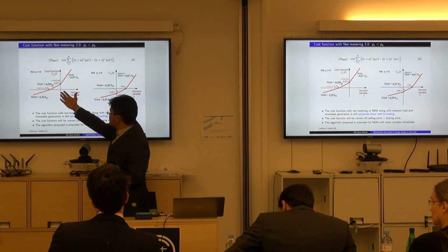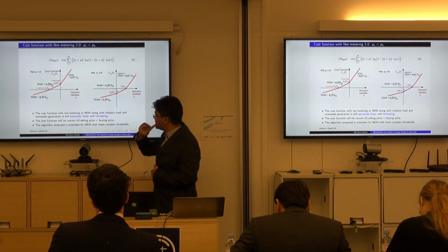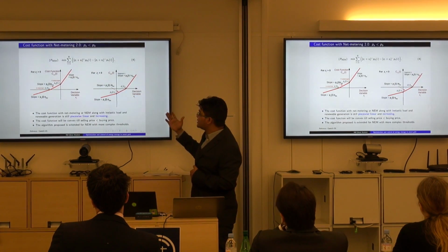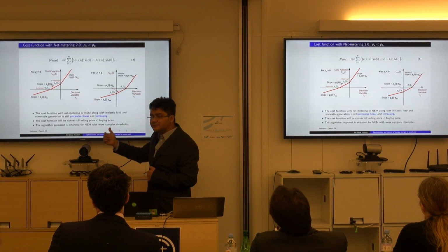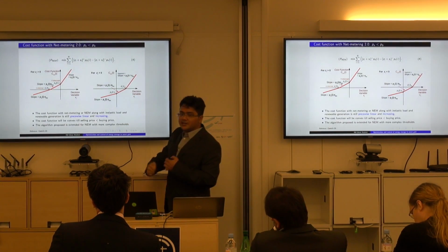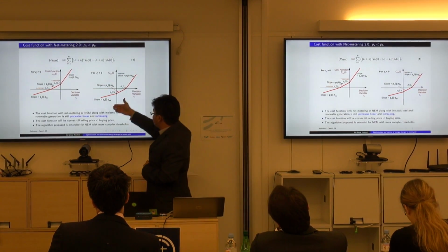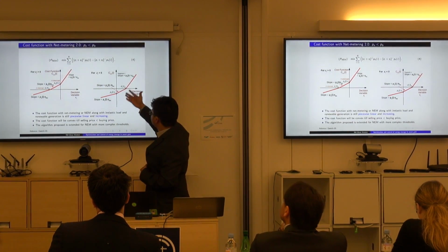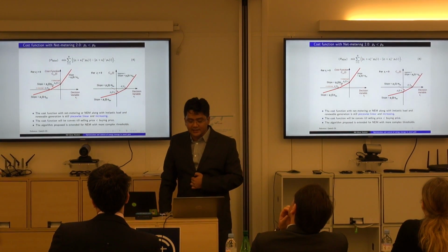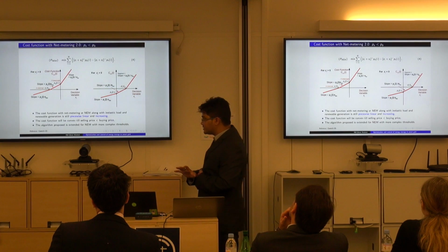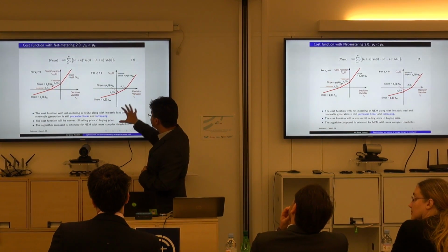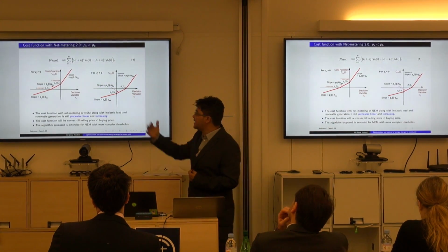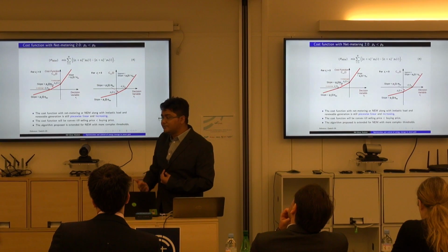If the net load is positive, then the structure of the cost function is as presented here, and both these cost functions remain convex provided PS, the selling price at any time, is lower than the buying price. We are lucky enough that the selling price is lower than the buying price in the policies that are designed. Because of that, we have convexity here, and the same structure of solution that we presented for net metering 1.0 can be extended to this with many more thresholds, because now the load and the sign of the load are important in deciding what battery actions should be taken.